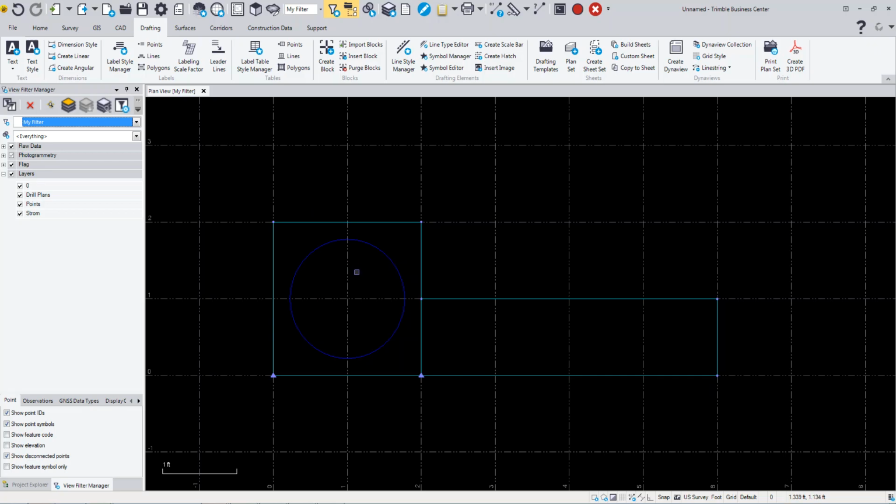And if you'll see here, they're initially starting out as just basically rectangles or polylines or circles. And you want to group them together and make them a block, so then you can insert that block repeatedly throughout your project and use it in surveying and mapping, or field to finish data reduction in your feature attribute library. So basically what you're going to do is draw the objects that you want, and in this case you might want to draw them to scale.